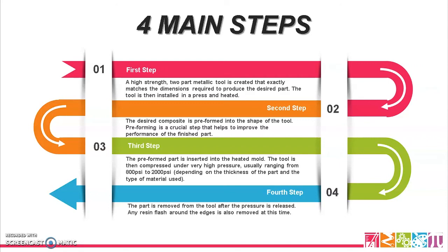Third step, the preformed part is inserted into the heated mold. The tool is then compressed under very high pressure, usually ranging from 800 psi to 2000 psi, depending on the thickness of the part and the type of material used.